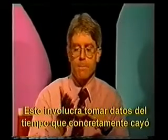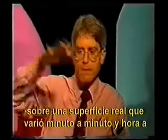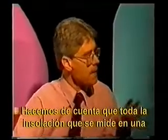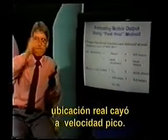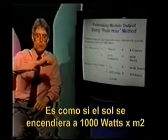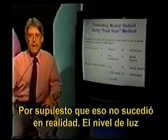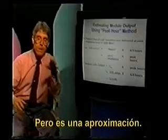What it involves is taking weather data that actually fell on a real surface, which varied minute by minute and hour by hour, and making a gross approximation. What we do is we pretend that all of the insolation that is measured at a real site fell at the peak rate. It's as if the sun from darkness turned on and shined at 1,000 watts per square meter for a certain number of hours, and then shut off. Of course, this didn't really happen. The light level varied hour by hour, minute by minute. But it's an approximation. Why do we do this?